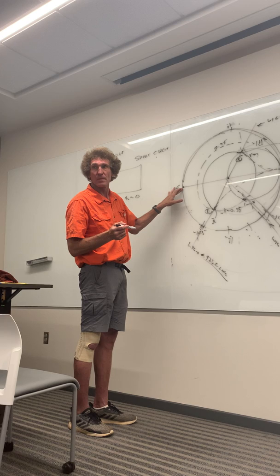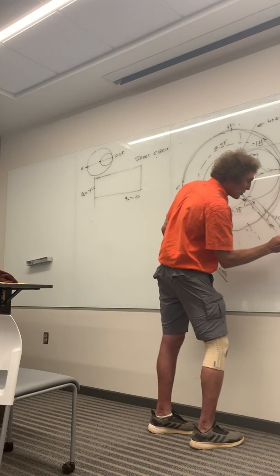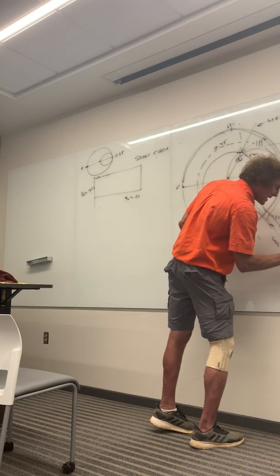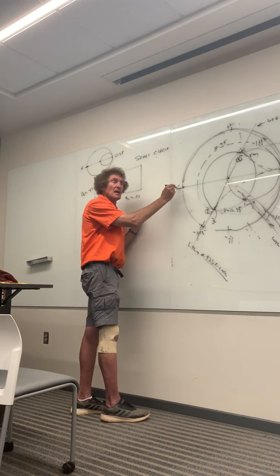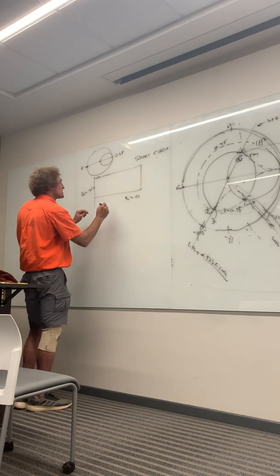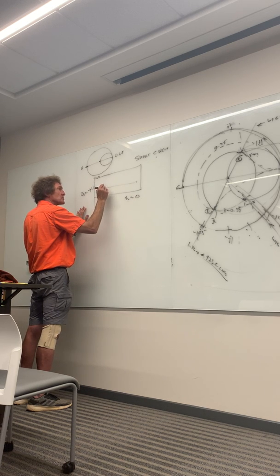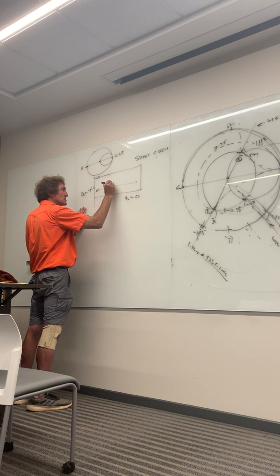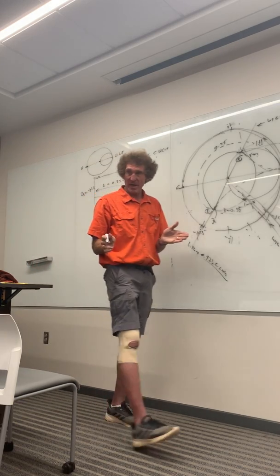Say it again. 0.338. 338. Can y'all see it? See what I'm talking about? This is 0.338 lambda. I started at 0 lambda, didn't I? Yeah. That means the length of this transmission line has to be 0.338 lambda. But then I get an exact match.